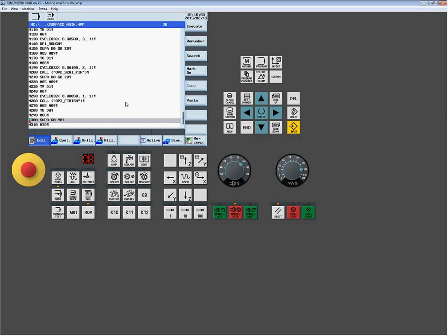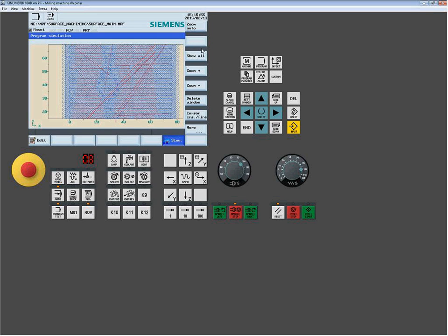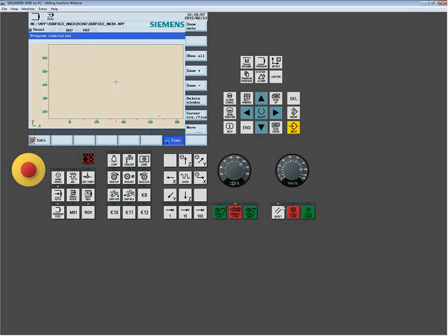You can certainly simulate these programs. If I delete the window, and if we were to run again, I can fire it up, and it's going to do what you saw before. So here it's already in and running the roughing cycle. And from there, once it roughs out, it's going to jump over to the other two operations. So even with subprograms, I can still simulate.